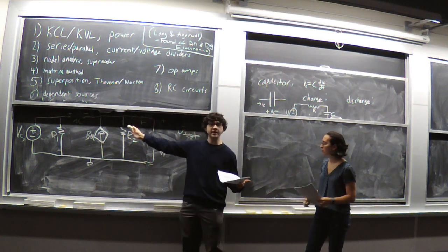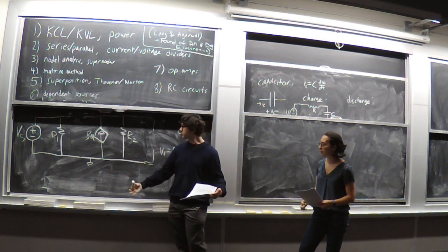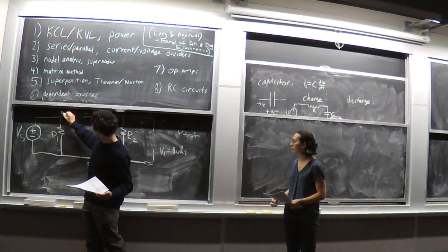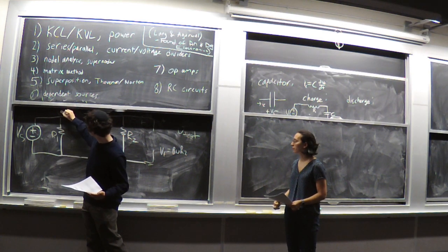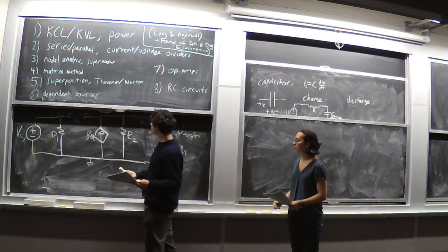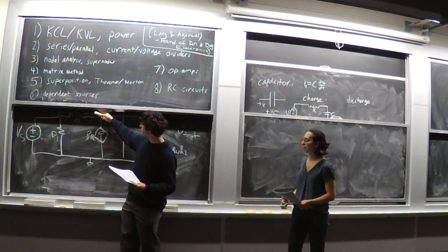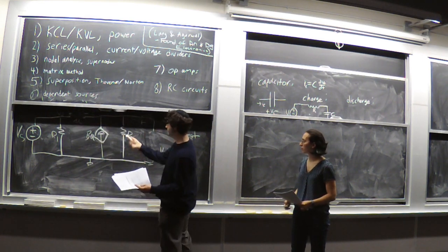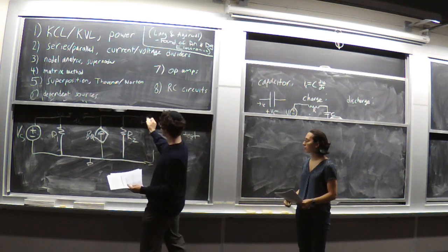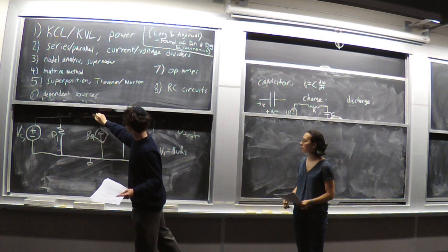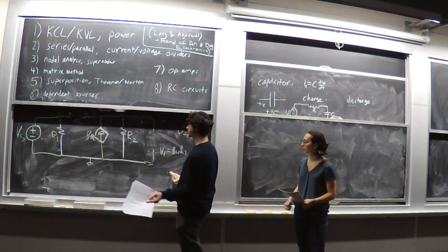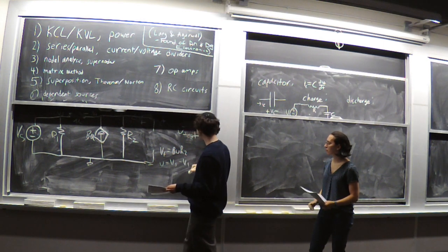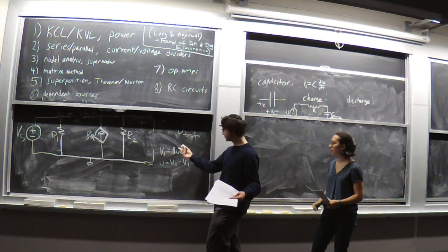We're not done because we can't use what U is. And so we have to come up with another equation. We can look over here and note that the voltage up here is Vs. In order to find U, we have to figure out what's at the negative terminal. U is going to be Vs minus whatever's over here. V-test is all the way up here. This is all one node. So if this is V-test and that's Vs, we also have that U equals Vs minus V-test. And now we have two equations for our two unknowns, V-test and U.